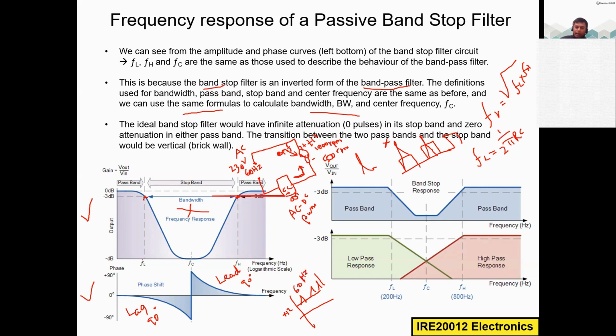So what I can do here is use a filter. I can use a band reject filter or band stop filter. The band stop filter I design will only reject 60 hertz. It will block these 60 hertz spikes, and I will get a very smooth plus 12 volts at the output. I add the filter here, get a smooth DC, apply it, and then I can control this DC motor speed accurately. So this is one of the functions.